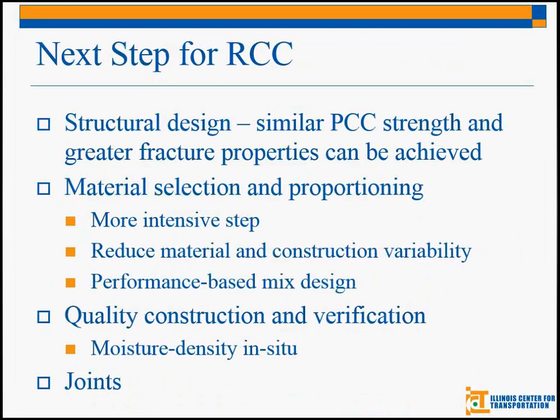All right, now finishing up, what is the next step for RCC? First thing to talk about is the structural design. It's kind of what I've hinted at for most of the time here. Do we need a thicker pavement? The answer is probably not, assuming that our engineering properties are similar to our conventional paving concrete.